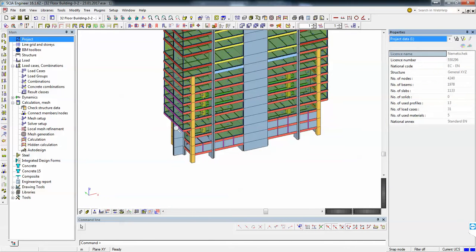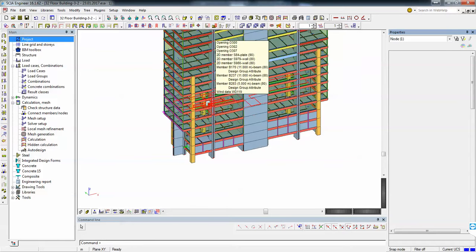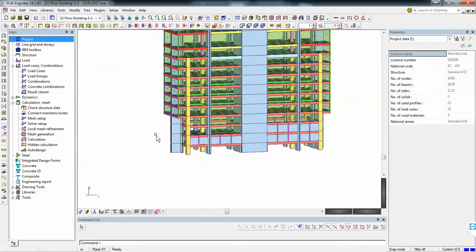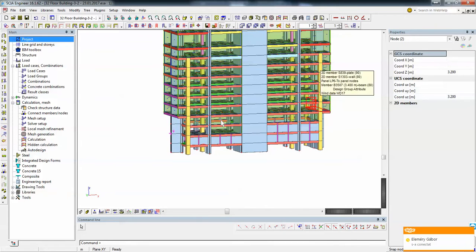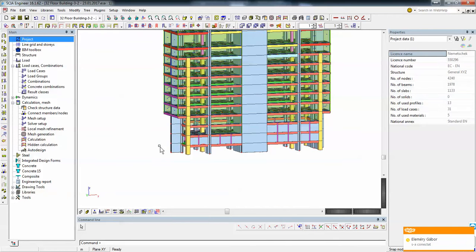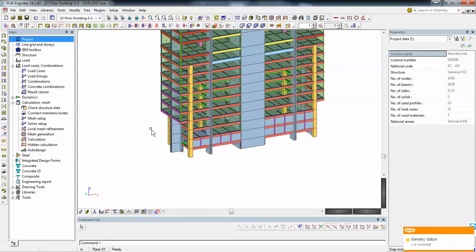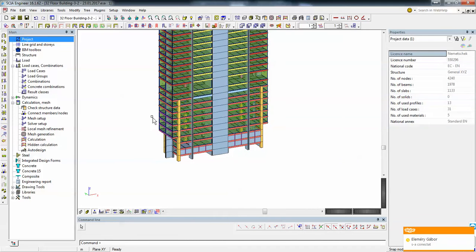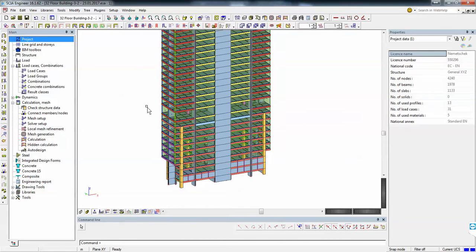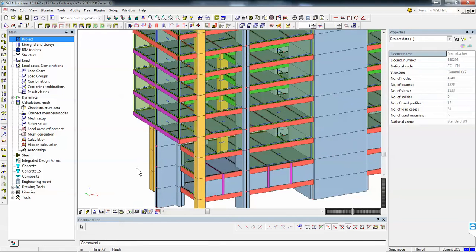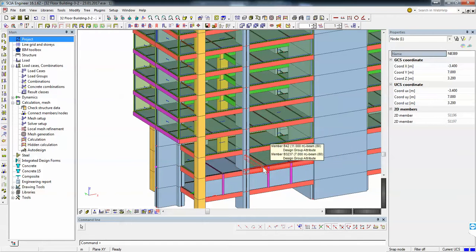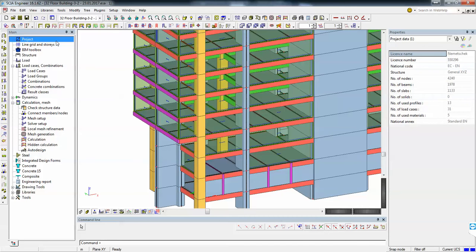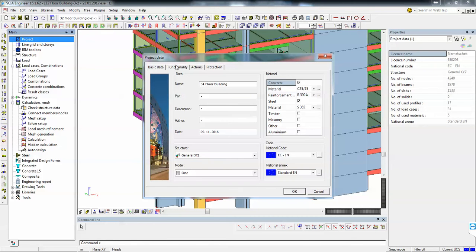So let's see here, 9 point. So I guess here can be 3.2. So then this is ground zero. So we'll assume the wind will act starting at ground zero. However, in your situation, as I see these walls, I understand that the wind will start at this 3.2. So this will be the lowest point from which the wind starts.